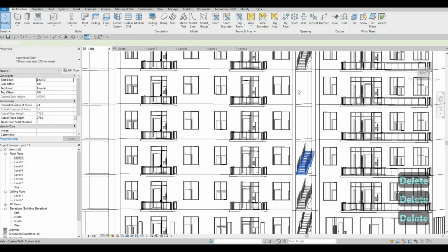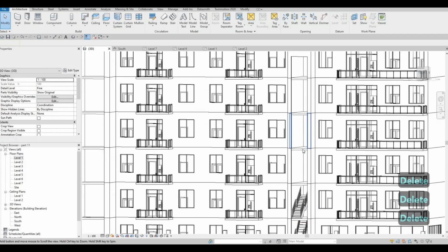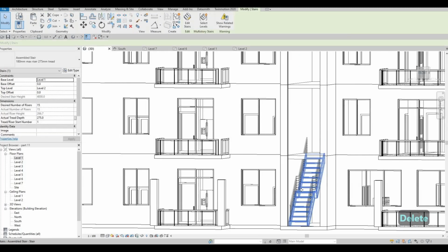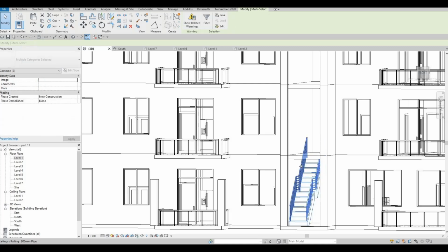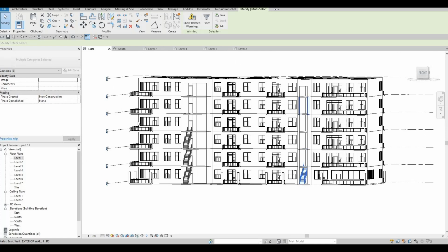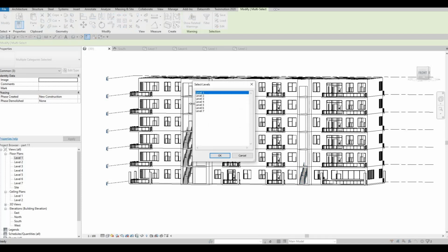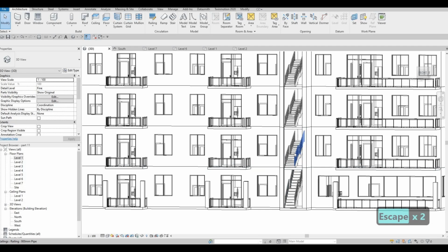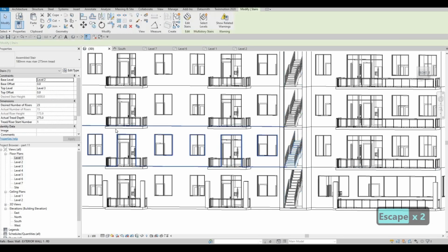And we could just double check everything. This one needs to go up all the way to level 6. So I'm gonna copy that, paste, select align, and then from 2 to 6, and then it will create those. And it's just giving us some errors. That's usually what happens. But if we could copy the way this one was set up, hopefully.